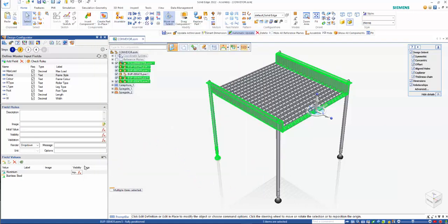So basically what we've done is we've set up a visibility rule to say that this will only be visible if the maximum load is less than 100. So we've only got the two options of 50 or 100. So the aluminium option is only going to be available with 50, but obviously if we add in other materials, or weight, sorry, that will come through as well.